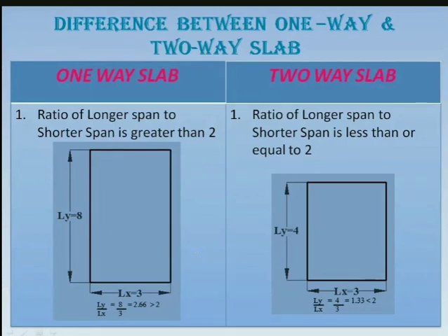So always remember that a two-way slab becomes heavy because main steel has to be provided in both the directions. So up to 10 feet, or in a residential building, as much as possible, we can try and avoid a two-way slab. Otherwise, the steel will become very heavy and the structure will become quite costly. So remember this practical thing. Anywhere if we are near 10 feet, practically provide the reinforcement in that direction.